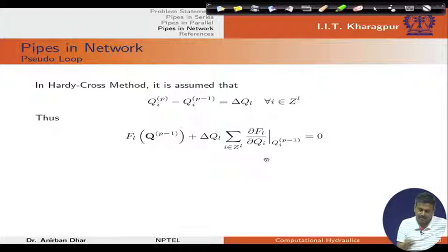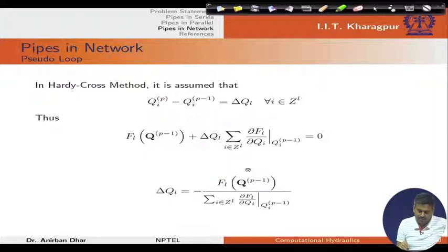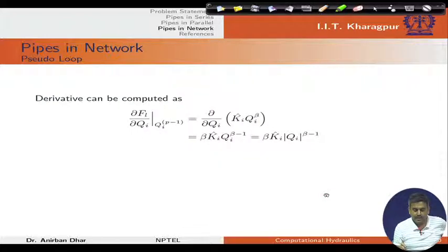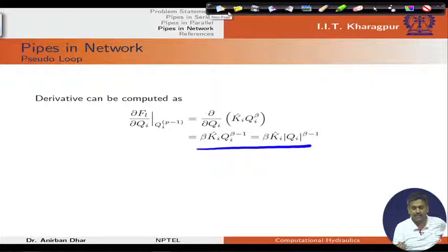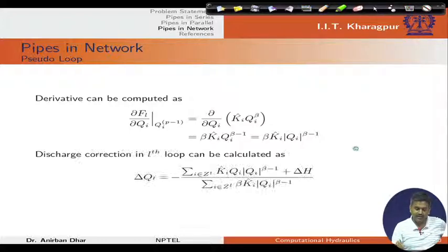This is similar to the previous one. So, this increment calculation expression is also similar to the previous one, but the only difference is the addition of the head difference term during del QL calculation. So, again we can find out the derivative, and derivative will be same because del H is a fixed quantity. So, there will be no effect of del H on this calculation or derivative calculation.